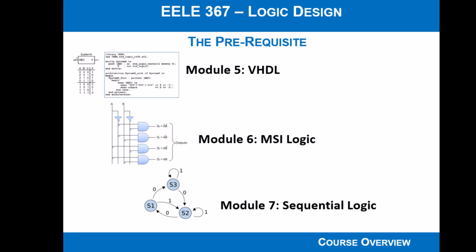Then we turned our attention to the modern digital design flow, which is using a hardware description language to model the circuit and essentially type out a description of its functionality, kind of like a programming language in that you use a keyboard, but not a programming language because you are actually describing the logic circuit functionality. Then we used a software tool, which was a synthesizer, which could create the gate level schematic for us. And that was a major breakthrough because it allowed us to do bigger and bigger circuits.